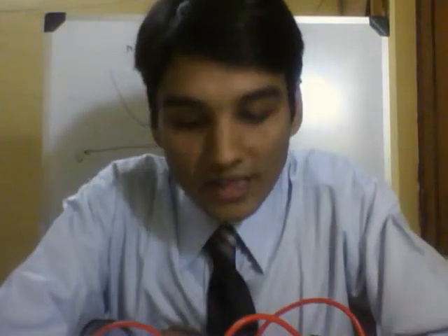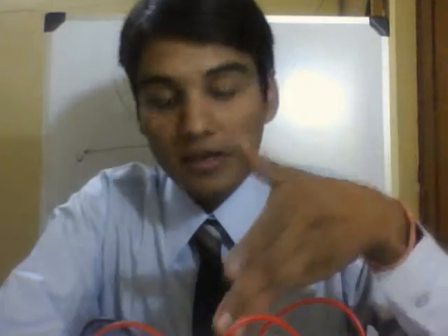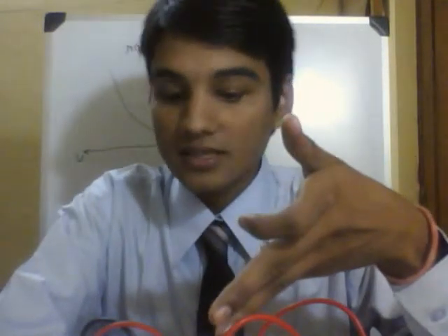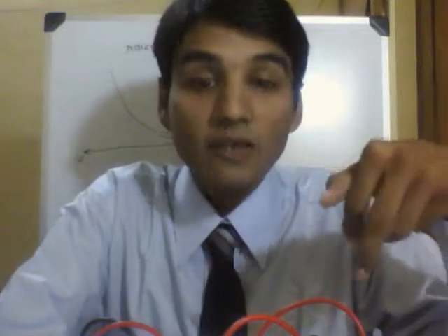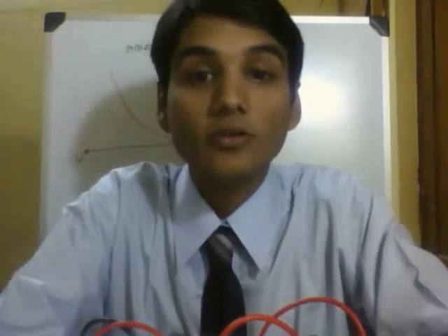Now, taking the example of the Zener diode, you have to follow the same instructions that we followed for the PN junction diode. Zener diode forward and reverse bias characteristics can be easily plotted by changing the value of voltage and noting down the value of current. And for the sake of economy, we have saved something by implementing the Zener diode in this particular kit as well. So three experiments will be performed with one kit.